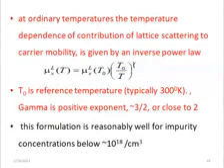The contribution of lattice scattering to the mobility of carriers at ordinary temperatures is given by this: mu xl of T equals mu xl of T0, where T0 is the initial temperature, maybe you can take it as room temperature, times T0 over T, where T is the temperature at the point where we are calculating that dependence of lattice scattering on semiconductor mobility.